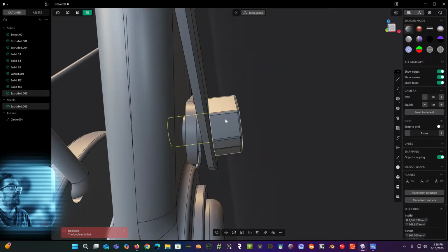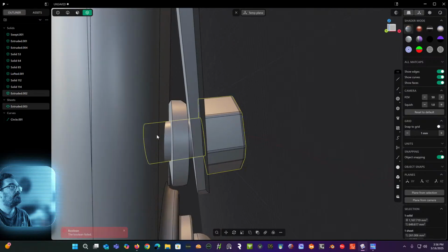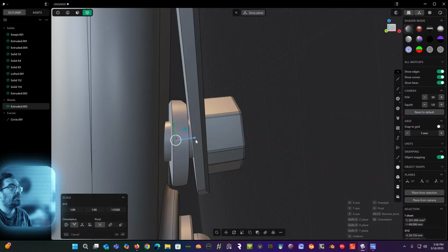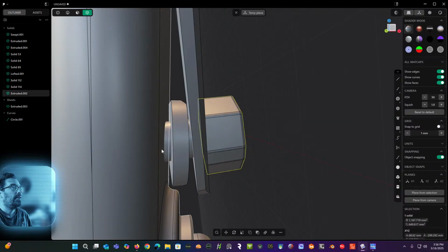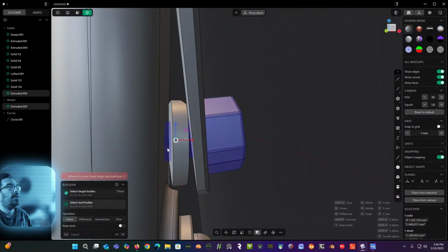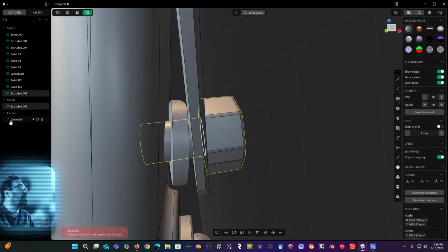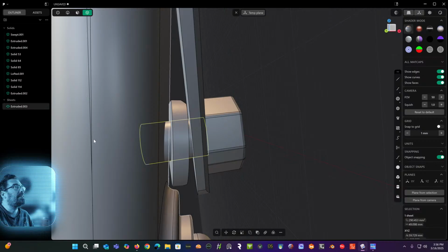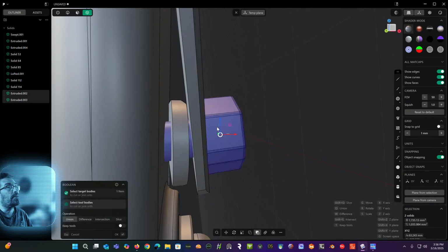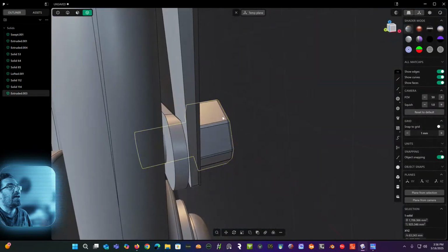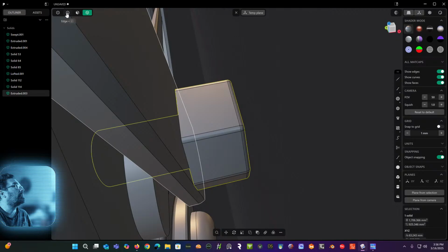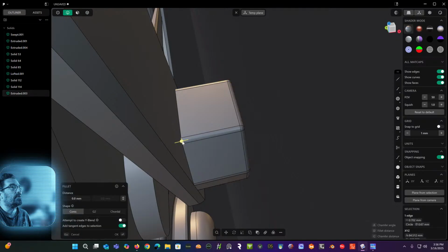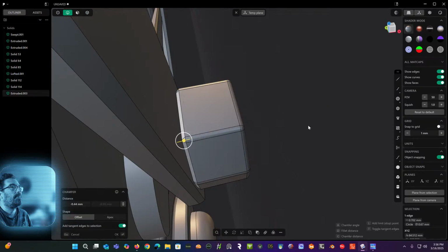Not sure why that's not going together. I'm going to take that here and scale that out along this so that it has more of an embedded nature about it. And we're going to go ahead. One's a sheet, that's why. So that circle can go. That one is a sheet. That needs to be made solid. So Shift J makes it now a solid, and then we can join the two together. And we're good. Okay. Yeah, knowing these little techniques makes a huge difference because it saves you hours and hours of time if you get confused.